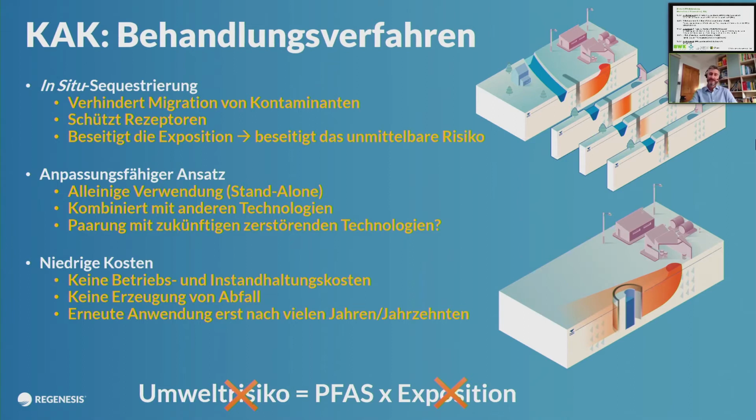It's a low-cost solution in that there's no operation and maintenance. You put the product into the ground, it's a passive solution. It will basically filter the contamination out of the groundwater for decades. So years and years, and then really when it eventually becomes saturated, 20, 30 years in the future, you're coming back to site and you're just re-injecting again. And that might be 1 or 2 weeks worth of work on site with a direct push injection rig. So there's actually very little work involved in giving you decades of treatment on the site.